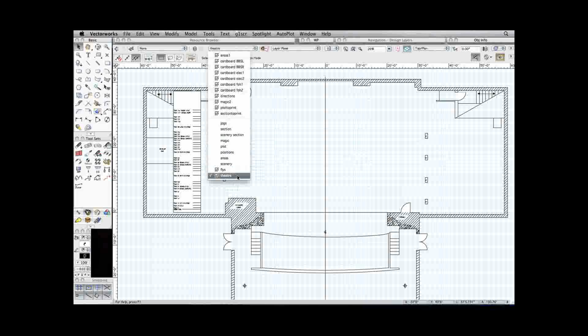demonstration today. So I do all of the drawing on particular layers, pretty much synonymously, as I said, with sheets of vellum. And then I use the second type of layer that Vectorworks Spotlight provides us with, known as sheet layers, as that top layer that I'm going to copy things up to that I want to then run off and print.